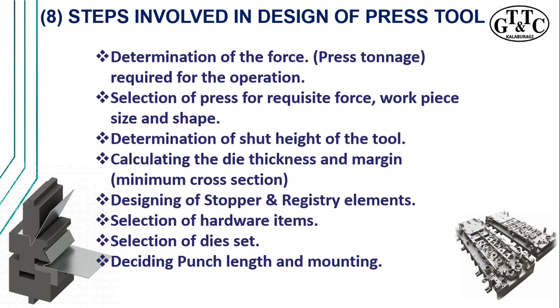So the information about the press has to be obtained from the customer, or if the customer does not have it, then it is the duty of the designer to give every piece of information about the requirement of the press to the customer. And then we see determining the shut height of the tool. The shut height of the tool is very important so that you can come to know whether it can be loaded properly into the press or not.